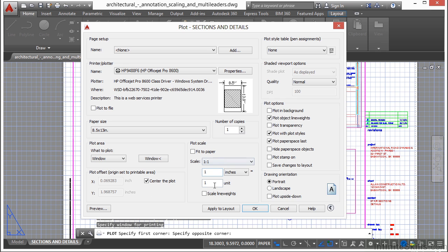Now the scale. The scale is very important. Typically, you're only going to print 1:1 because you use your scale in your CAD file through your viewports. That controls the scale. And paper space is set up as if you were drawing in paper. So everything is scaled in there automatically by default according to how it's going to look on the paper. You define your text size, how it's going to look in paper. So if you want your text to be 1/8 of an inch high, then that's what you set your text to be, 1:1. Drawing 1:1 in AutoCAD is the key, and it keeps everything simplified that way. So typically this is going to be 1:1.